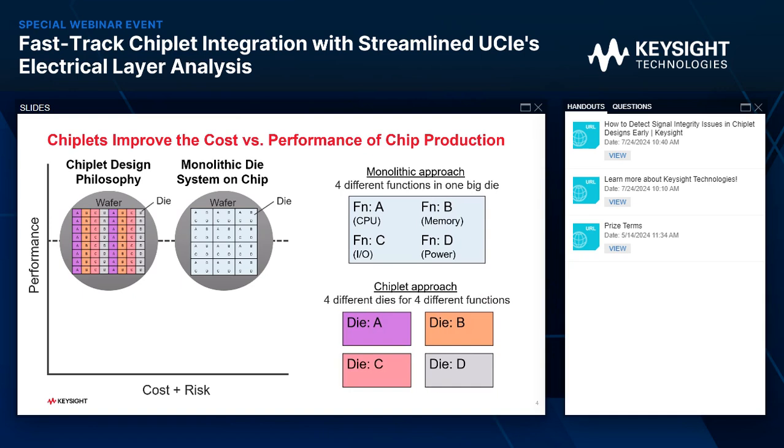Now, if there are 4 defects on the wafer for the monolithic approach, and yes, there will always be defects, the big die would have a yield of only 66.7% if we do the calculation. From 12 chips designed, we produce 8 chips, and the yield is 66.7%. On the chiplet design wafer, given the same 4 defects, we'll have a yield of 97.3% because the die sizes are smaller. When one fails, it does not impact the entire production that much.